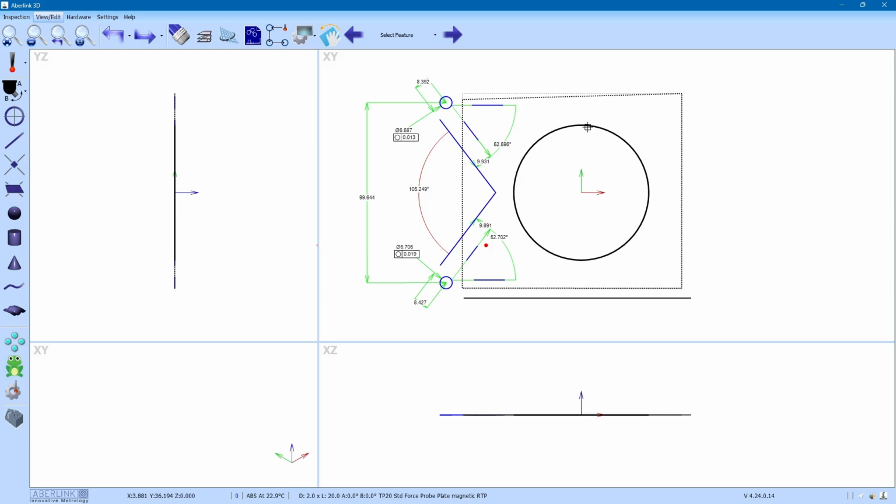Now, obviously I don't have this in this example. I don't have a physical line or physical plane running through the center of the part on the y-axis to be able to mirror from. So I'm going to show you some tricks to construct those features, and then we can use the mirror array to copy the features. Firstly, we want a plane running through the middle, but we can't do that without having a line. There's a few different ways we can do the line. I'll show you two examples right now.